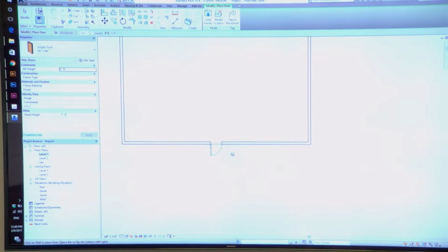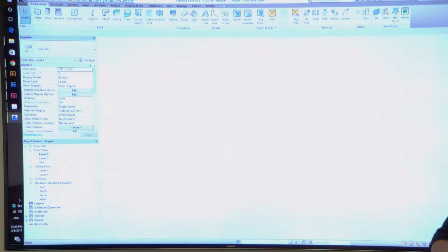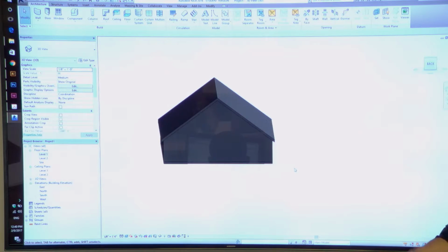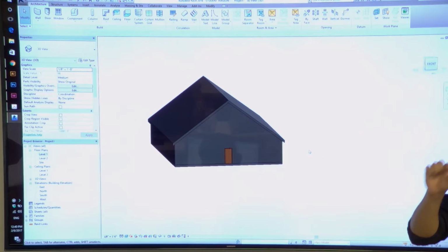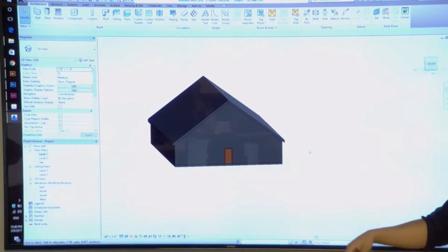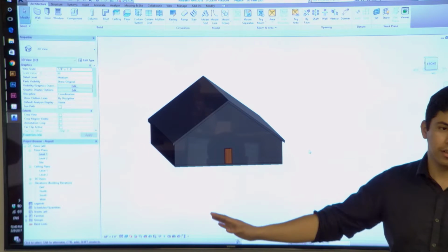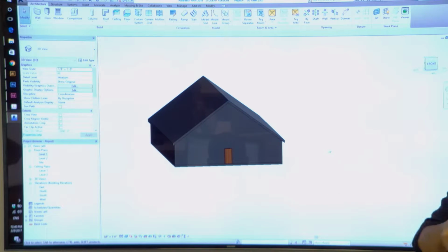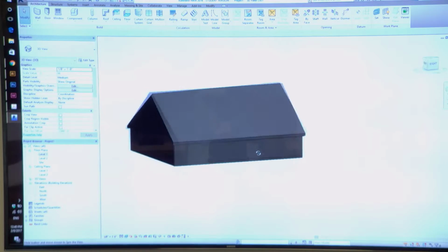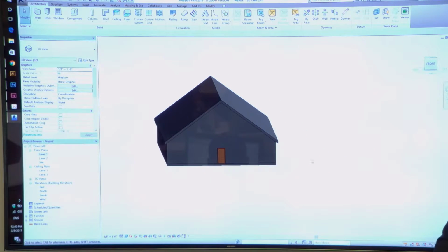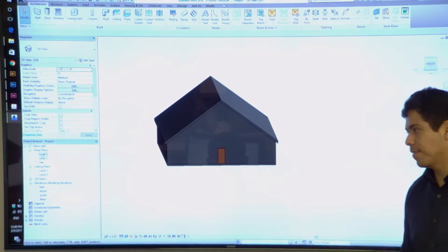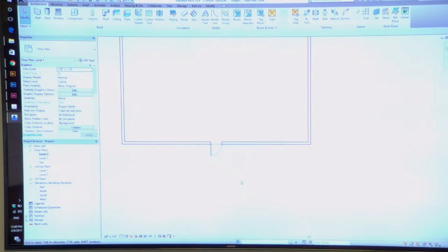And hit OK. And if you go in your 3D view, because it's always nice to go back to your 3D view to just get an idea of what you're doing. And see, it makes a door on your level 1 on top of the floor plate, and it's flush against the wall. And if you look at it in plan, it'll give you the swing, like how far out it swings. A lot easier than actually having to make the circle, guessing the radius. All right. Faster. Does anyone have questions yet so far, or everyone's good?